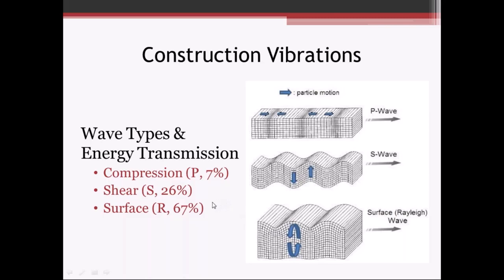But something to point out here, with these Rayleigh waves, the surface waves, most of the energy is transmitted through them. About two thirds of the energy is transmitted in those surface waves. So those are really the ones that come into play most of the time when we're monitoring construction vibrations, and it's those surface waves that travel along the surface of the ground.